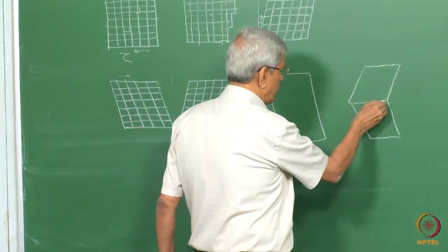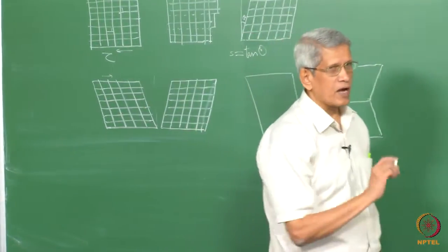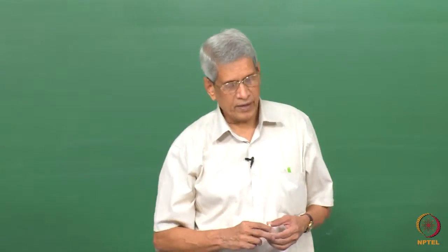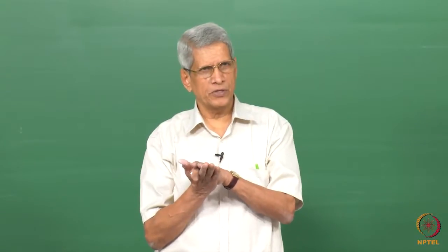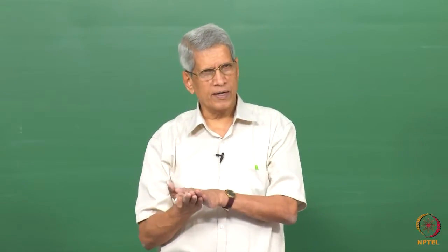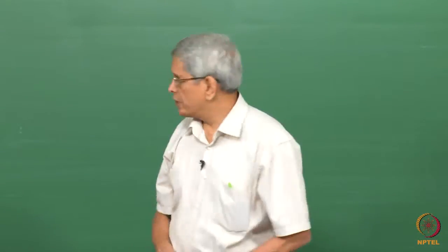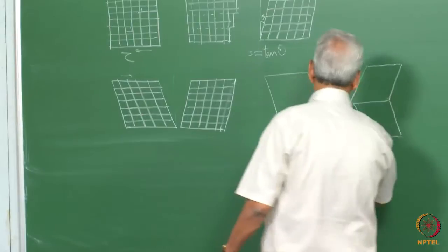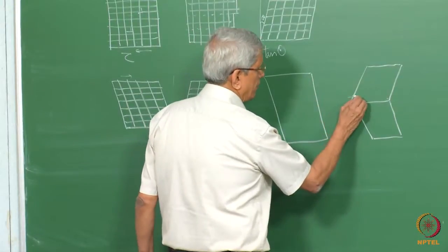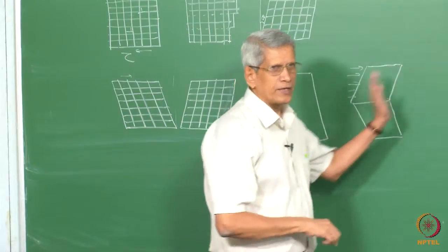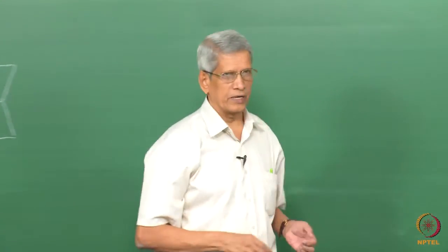So this plane where they join together is called the composition plane. That is where the twinned and the untwinned region meet, or this is also called the twinning plane. Essentially across this plane, everywhere a homogeneous shear has been applied. That is how this deformation has occurred, correct?